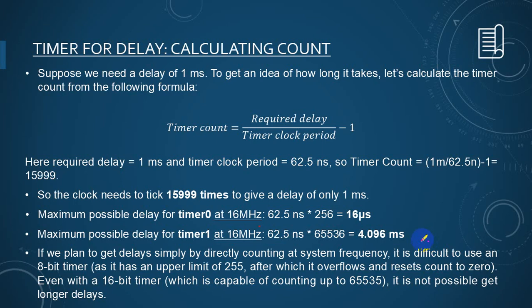Basically, what it does is increase the cycle time of each count. As it increases the time of each count, overall, with the 256 counts, you can count more time. In a similar way, with 65,536 counts, you can count more. So that's the main technique for pre-scaling. Okay.